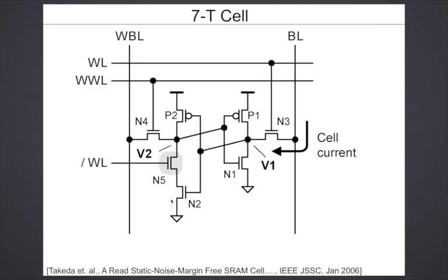It will have an impact of maybe 50, 100 millivolts or something. So the scaling of the voltage is not really limited by that asymmetry out here. It's really limited by the loss of noise margin due to process variation, plus minus 5 sigma. Some cells are so bad, there's so much deviation in the characteristic, that that limits how low you can go.